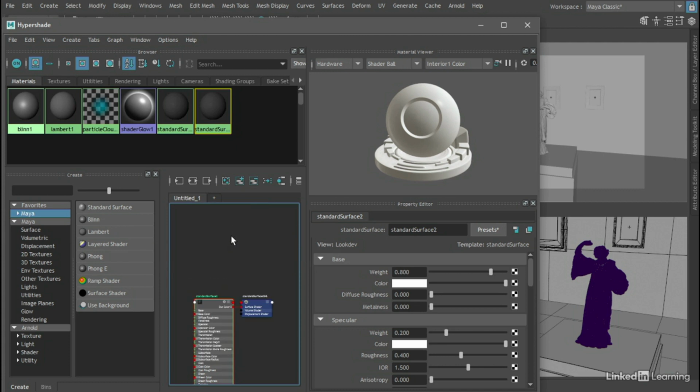That option is stored in every individual scene for the Hypershade. So if we turn that off and then open a new scene, it will probably be turned back on again. The node editor does have a user preference for this, but the Hypershade does not. That's how to control whether or not new nodes are added to the graph.